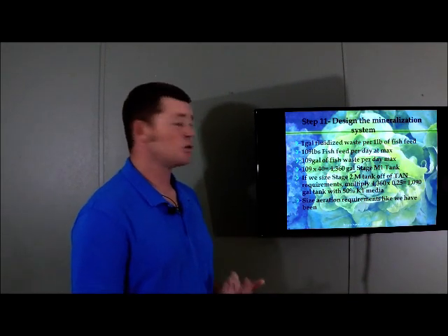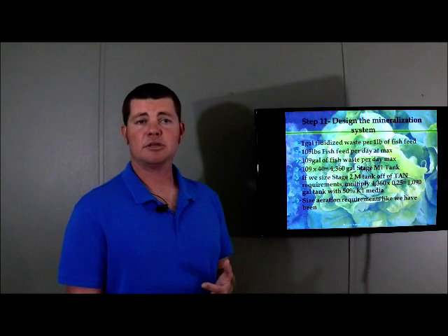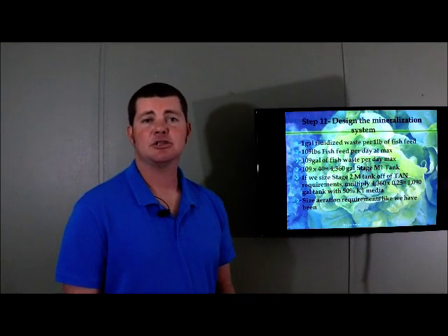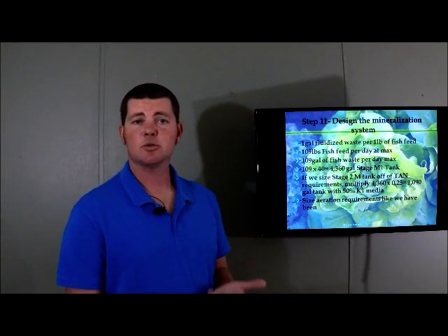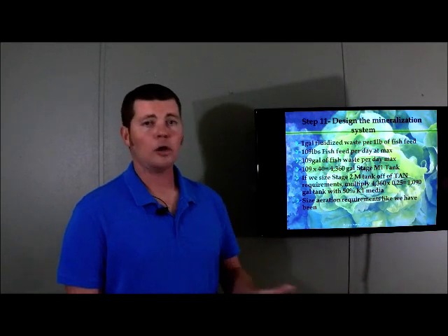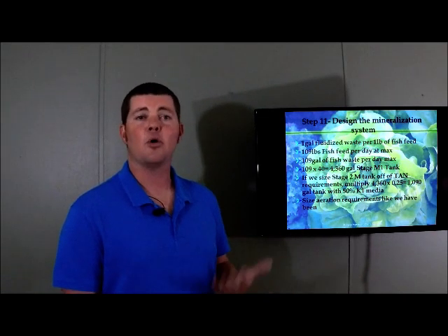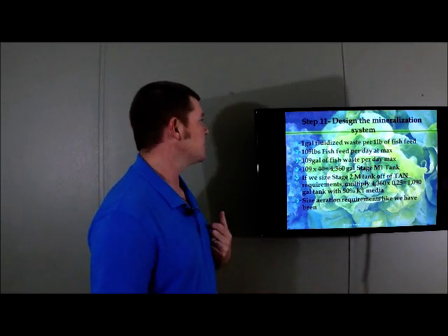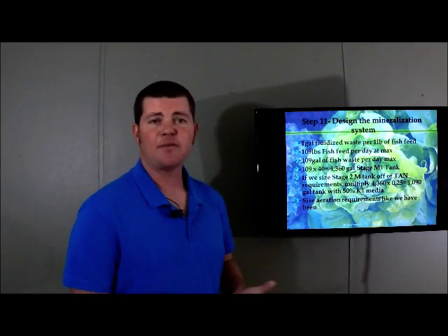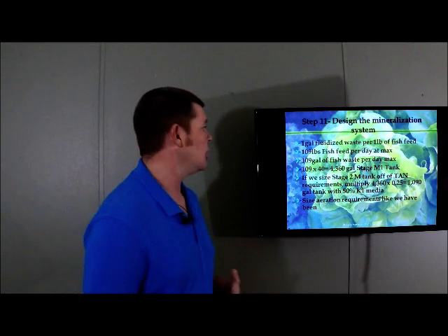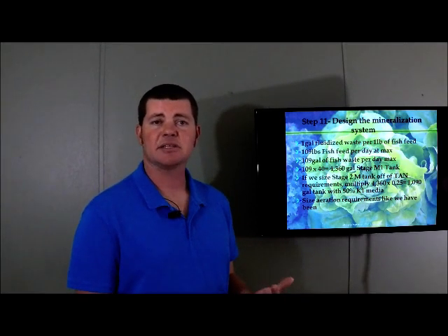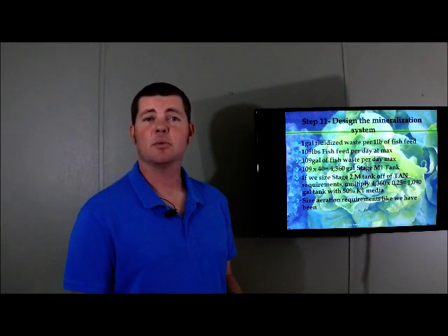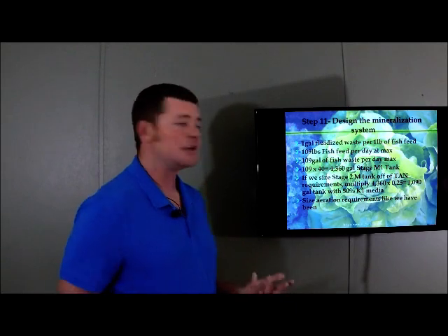And again, because we're doing lettuce here, we're going to favor the higher oxygen concentration in our stage 1 M tank and do all aerobic nitrification and aerobic mineralization. We don't need anaerobic properties to supply extra phosphorus, and break that down and supply it to our plants. What we need is the nitrogen. That's really what we want because we're growing leafy green vegetables.